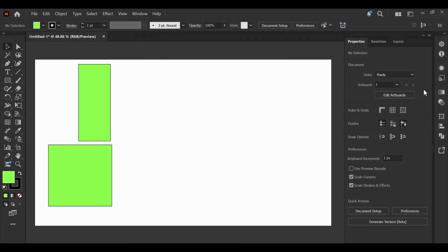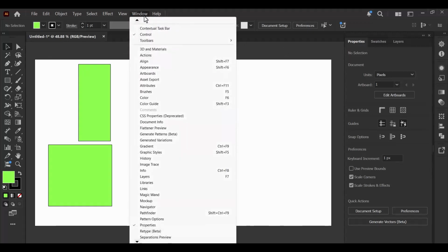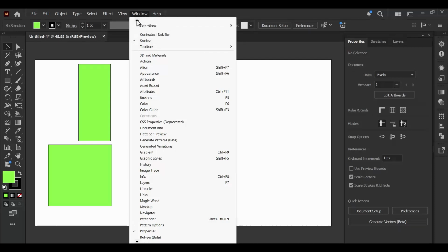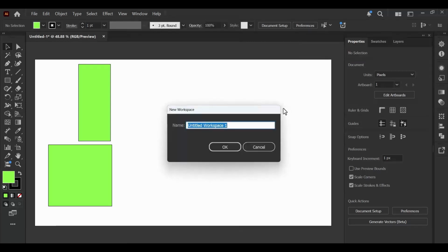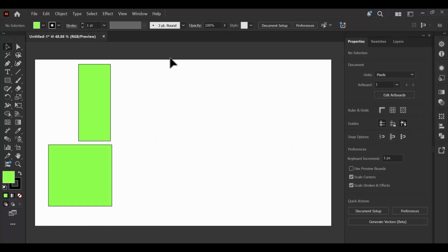Right. So once you customize your workspace according to your own requirement, you can then further save that workspace for your future reference. So you no need to enable and disable and arrange all the options again and again and waste your time. You can simply create a new workspace according to the custom requirement. Go with New Workspace. When you click this option, we can find the panel in which we have the option to define the name of the workspace. I'm going to set this name as My Custom. Click OK to confirm. So we have one workspace already defined.